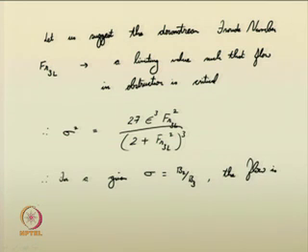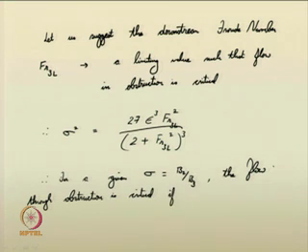the flow through the obstruction is critical if the downstream Froude number is equal to this limiting Froude number. Fine, that is quite obvious, right? So, if Fr3 is less than Fr3L, that limiting value, what happens?